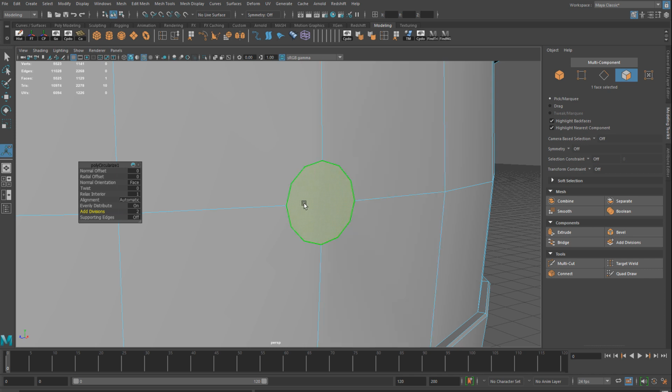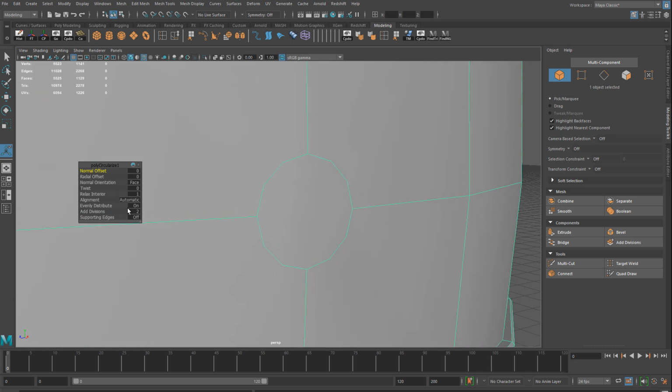And actually, I can use this as a cork already. So I'm going to select this face. Oh, let me go back to options. Anytime you want to bring options back, if you close them down, just hit T. Let me go back to object mode, hit T for transform or tool, and it'll bring that menu back. So here I can go back and re-enter.